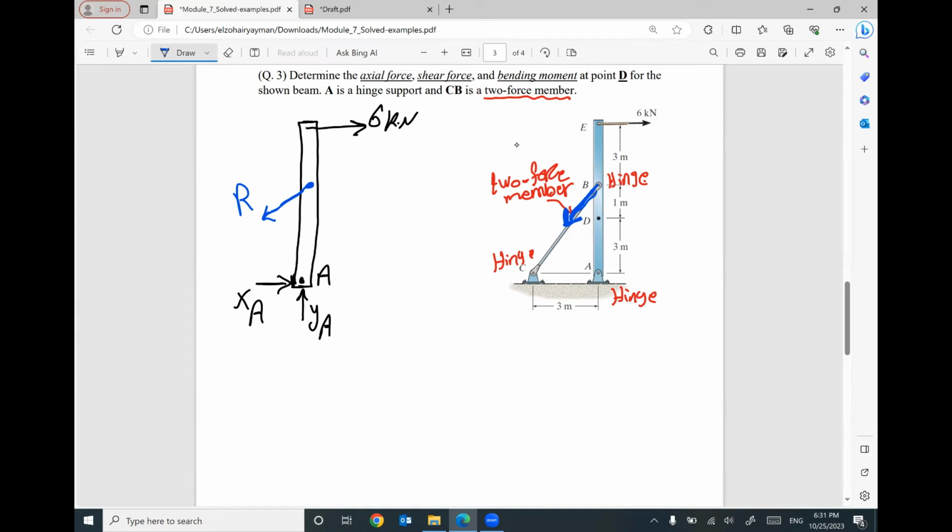So how to solve for reactions? If you have this member in your structure, which is called a 2 force member, go ahead and remove it and put at this contact point B one reaction. In which direction? In the same direction as the deleted member.